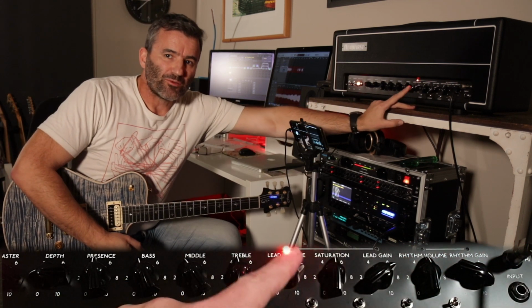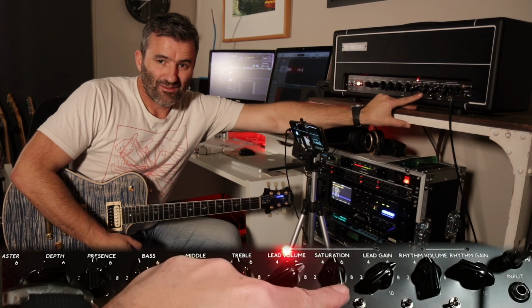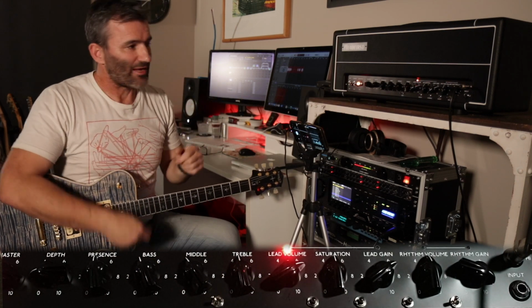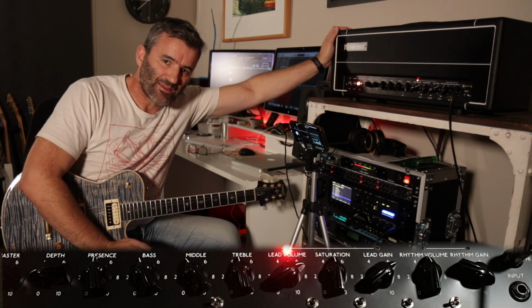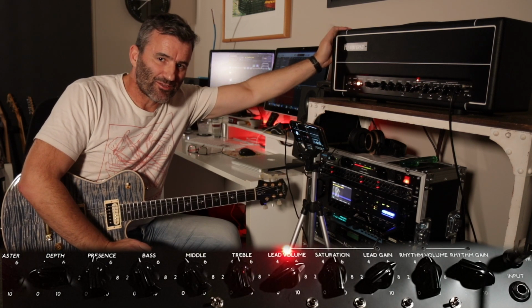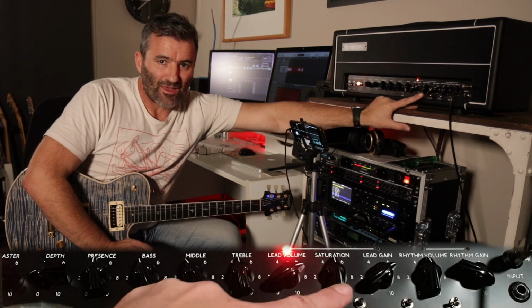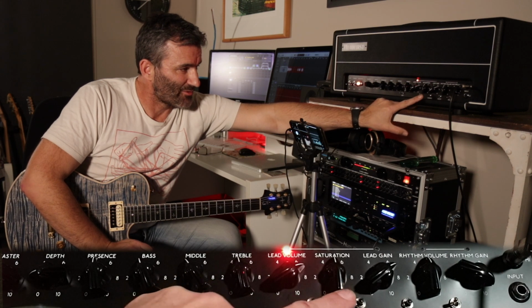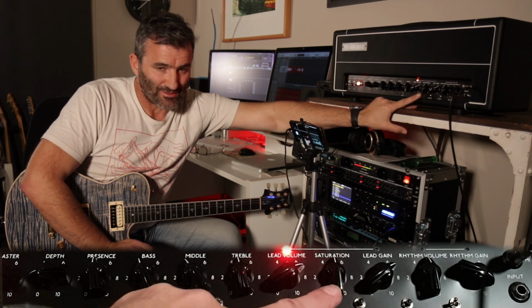On the lead channel, we have the saturation pot, right? This is basically controlling the gain of a gain stage that's kind of in the middle of the preamp. The difference between, in the Wizards, the MTL and the MC2 is this extra gain stage, right? So you can think of the saturation control as an extra, adjustable gain, and it's really controlling the gain that's coming from, as I said, that extra gain stage.